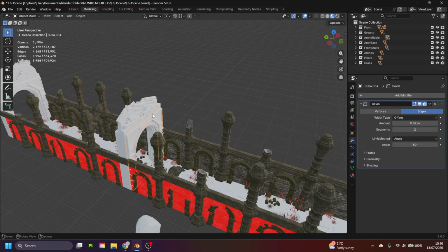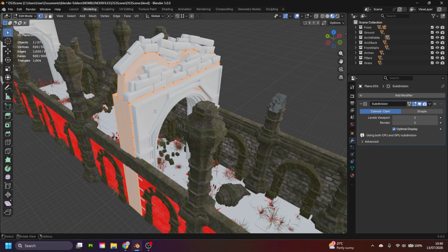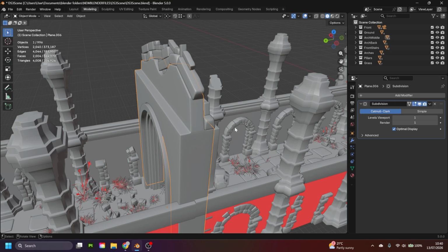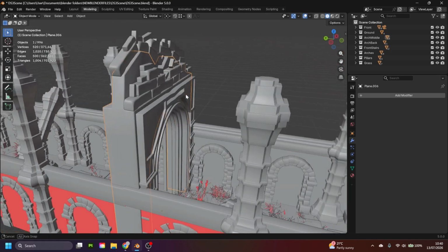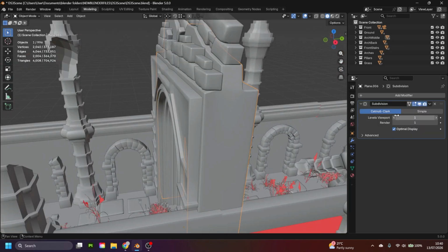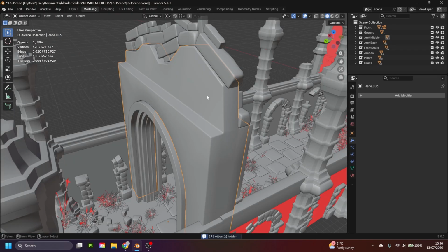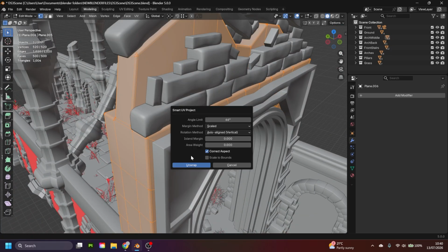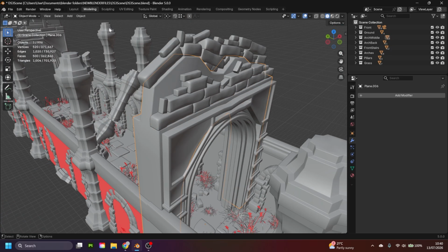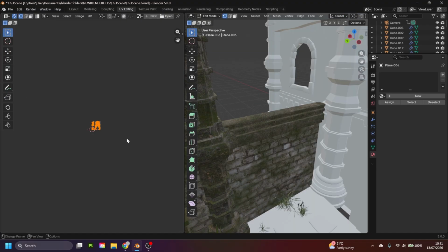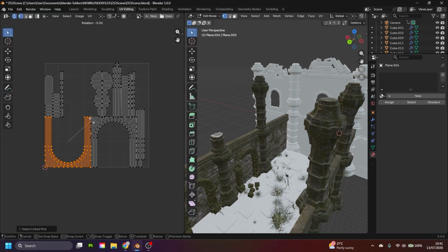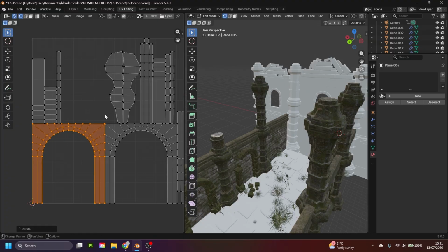And then for this large building here, it's going to be a bit annoying to texture because it's a stranger shape and a lot bigger. So the easiest thing to do would be to, also just checking out, I don't think I need this subdivision modifier one really. It's not actually making too much of a difference. So I'm going to turn that off, so we just have a much simpler mesh. Something like this, I think a smart UV unwrap should be fine, because it is generally quite a simple square shape. See what that looks like. I think that looks alright. Might need to just turn this face here around, which I will do now, so at least the textures will be facing the right way.